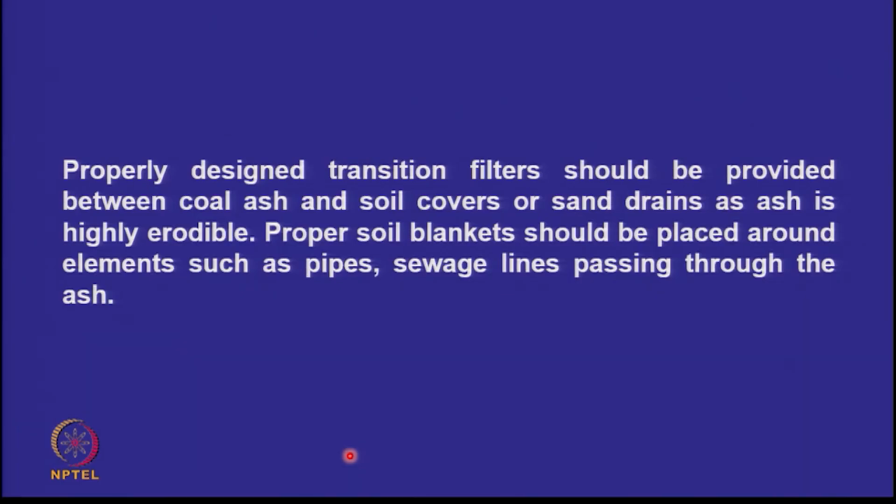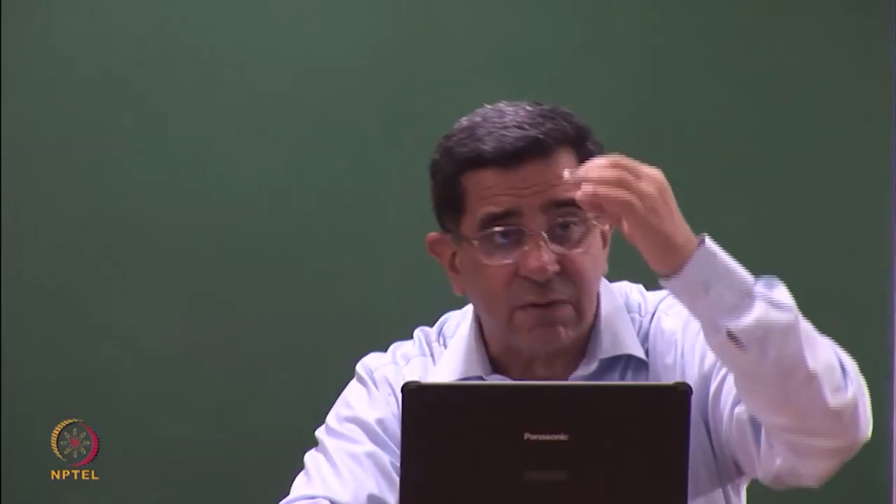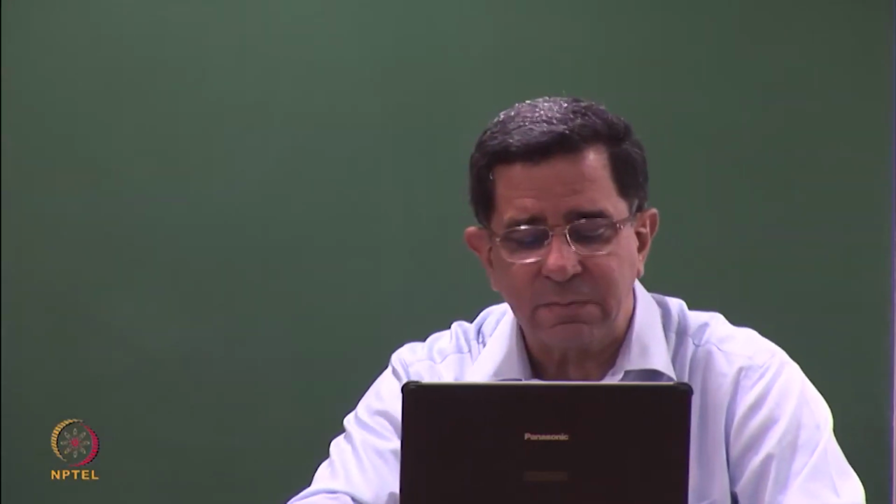Critical to ash and mine tailings performing well over the long term are properly designed transition filters. The fines should not get washed out to start piping. And another important point is that if you are burying pipelines in ash or tailings, you may like to put soil blankets around them, so that even if there is a little bit of crack or a fracture, the material coming into the pipeline is soil, and you do not want ash to run into the pipelines.